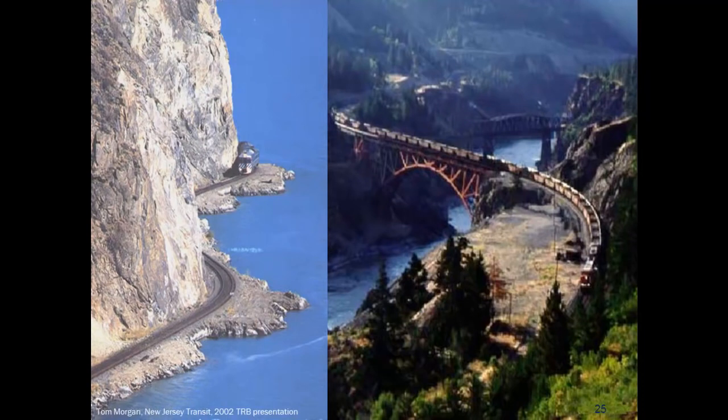Okay, so for those folks doing planning, installing passing sidings is expensive, right? Yes, you are effectively building a 2-track railroad here and there. You must consider the location and topography. In mountains and in cities, it is difficult simply because of the space required to build it. Curves, should be noted, constrain capacity.